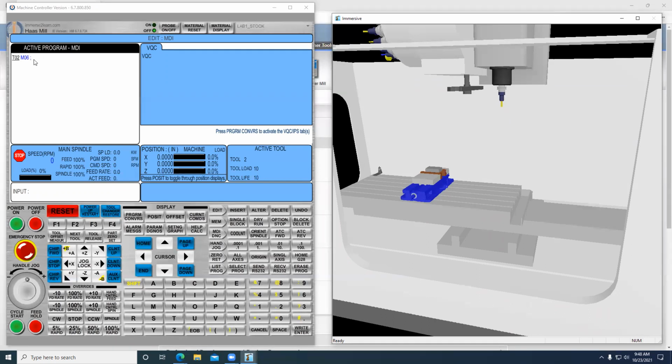In this program, we can make it as long as we want. So for example, next tool will be, let's say, tool number 3, M6, and end of block. Again, after pressing enter, you see in the window, the program is not structured correctly. So if we go back, we can erase the program.